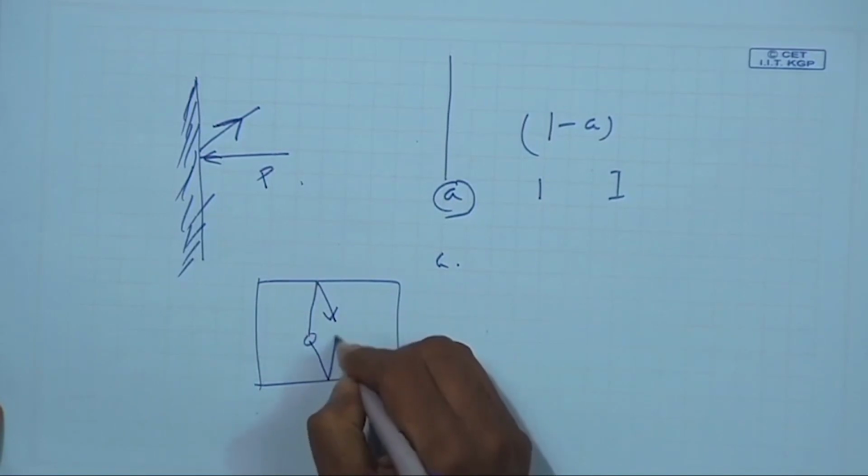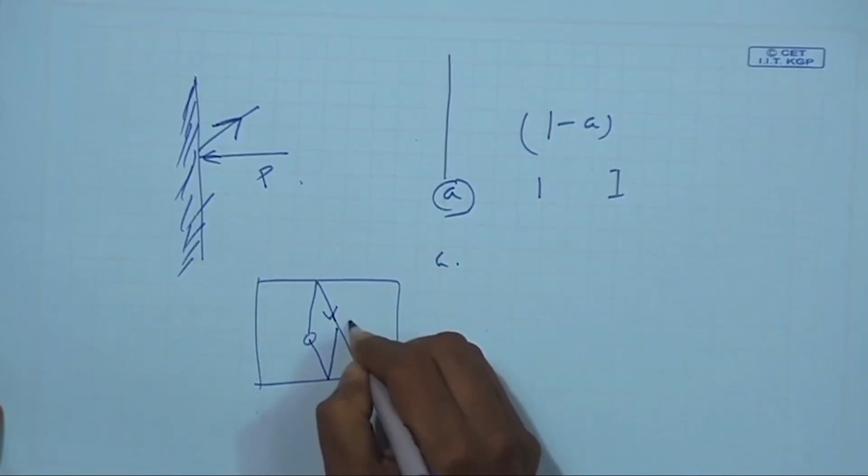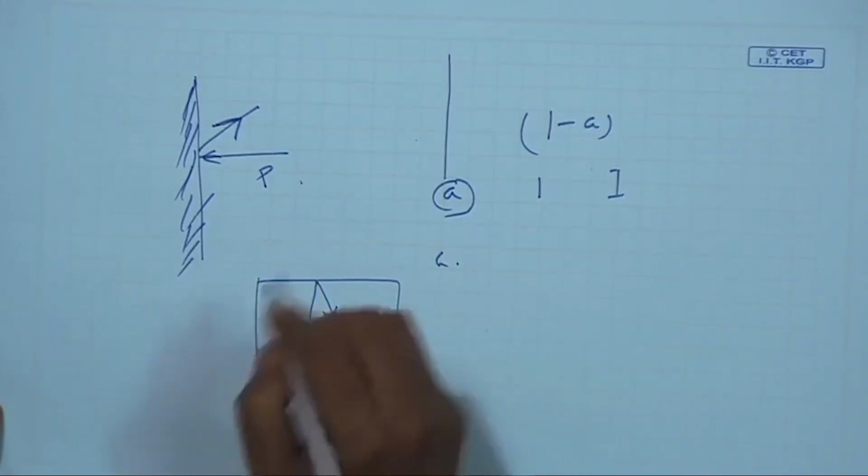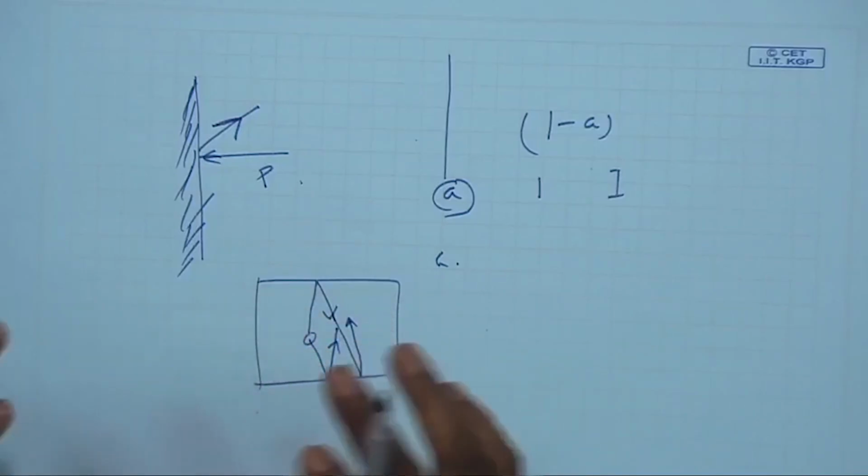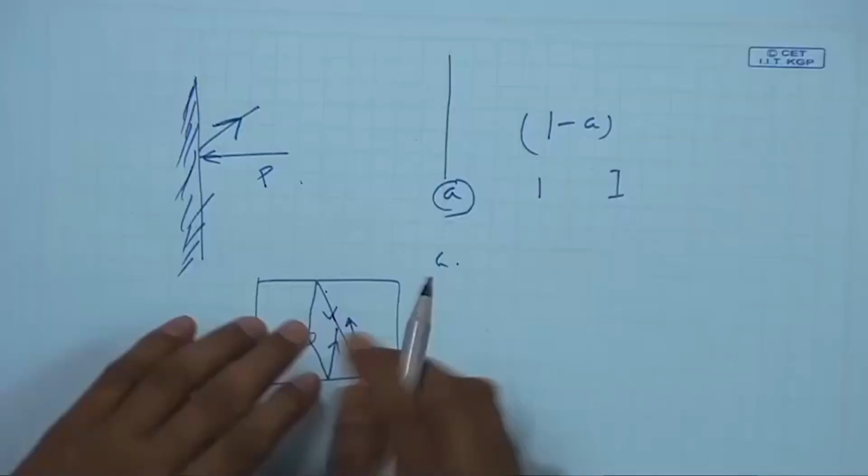Similarly, it will fall on this wall, then this reflection will fall on another wall, then will create a reflection. All reflections create a sound pressure level. If I switch on the loudspeaker in this room, for some time it is required to reach the steady state level of that room sound field. Since there is absorption, it is a semi reverberant field. So, the sound pressure level is reached in a steady state.